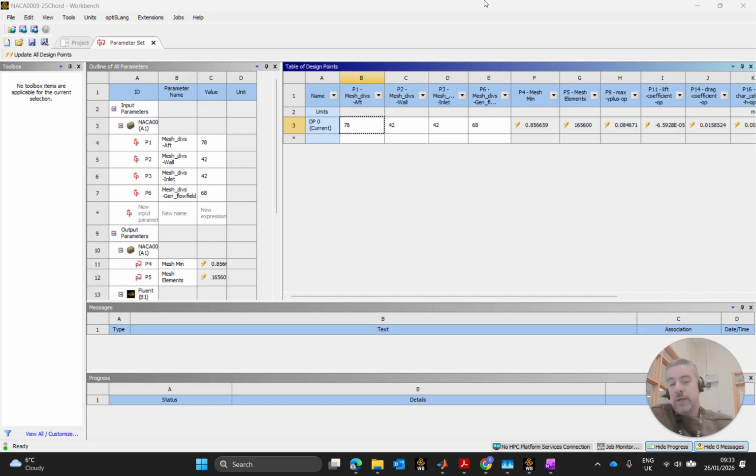Okay, so you can do that, and then when you effectively see that flat line, you can say, yeah, things have converged. That's fine, but it doesn't really give you the same sort of insight that the grid convergence index method, as laid out by P.J. Roache, does give. That method not only tells you something about convergence, but also about how your model, the physics, your numerical method or discretization scheme, and even your turbulence models are working.